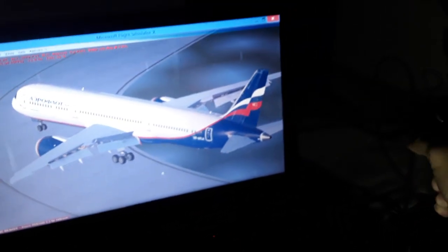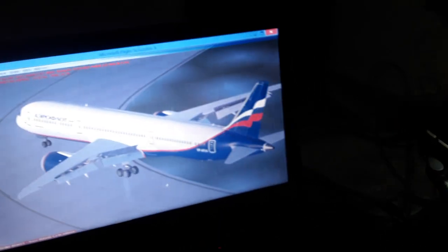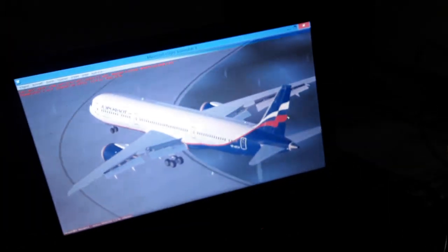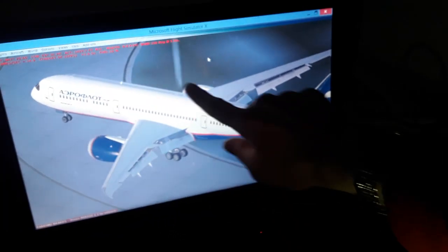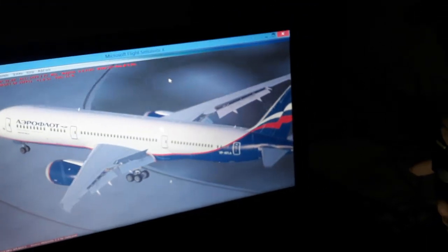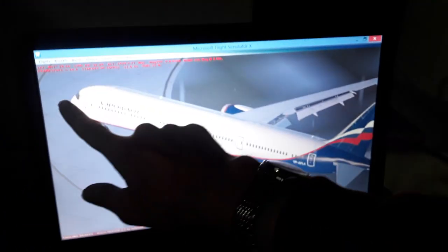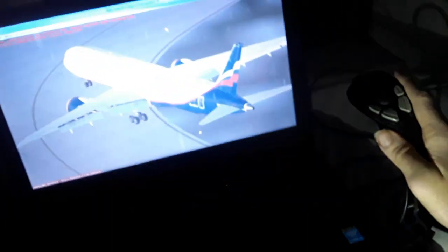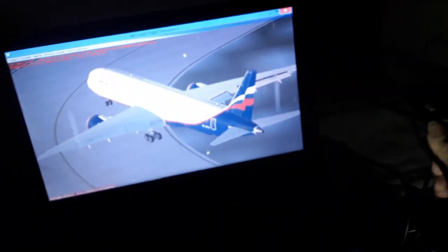So you have the pitch axis, you have the yawing axis that traverses the center of gravity over here using the tail, the vertical tail, and you have also the thrust from the engines, the jet blast propulsion from the jet engines right now, of the Boeing 787. And you have also the longitudinal axis from nose to tail over here, which is actually the roll axis. So the roll axis is for controlling the aircraft using the ailerons and the spoilers, making left and right turns like this. As you can see, roll axis.